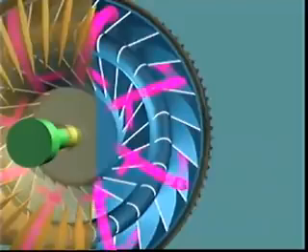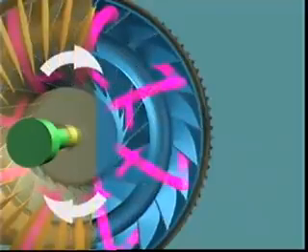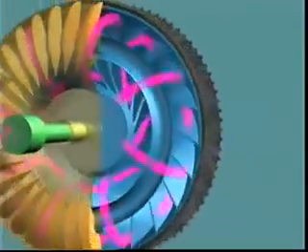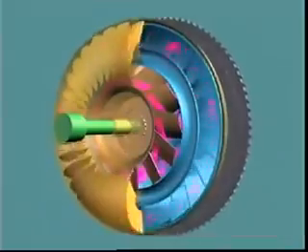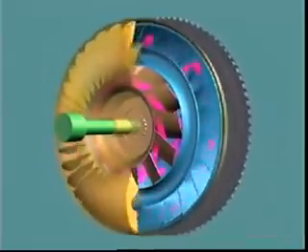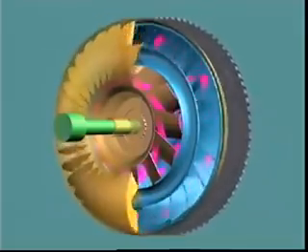The fluid, still at high velocity, now flows between the turbine vanes, leaving the turbine in a direction opposite to impeller rotation. This is due to the curvature of the turbine vanes. Unchecked, this would oppose impeller rotation and reduce turning effort. To defeat this, the stator redirects the fluid. It re-enters the impeller in the same direction as impeller rotation.